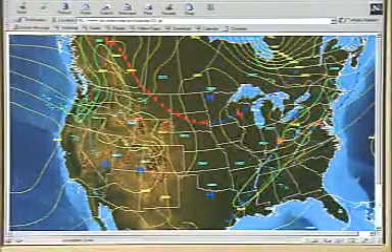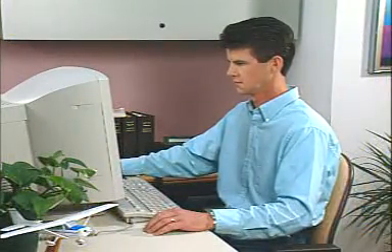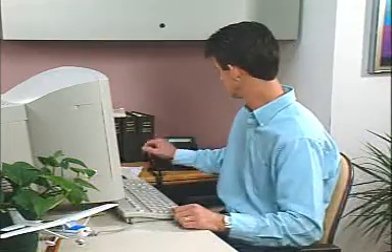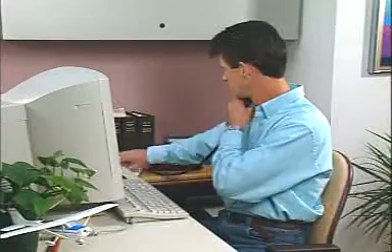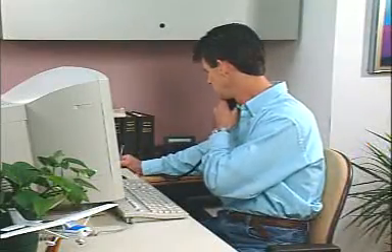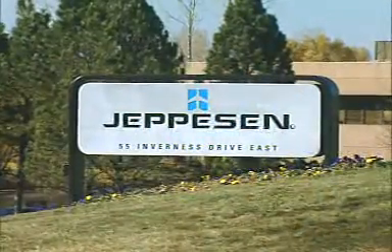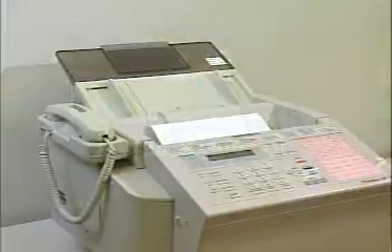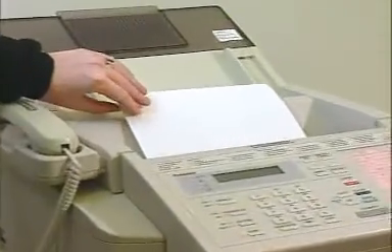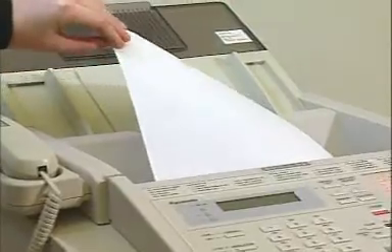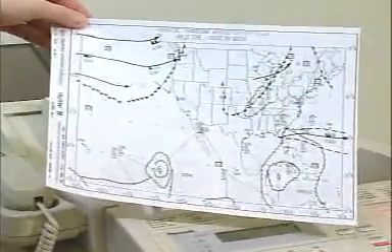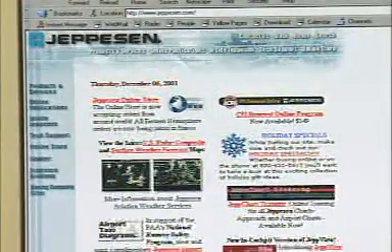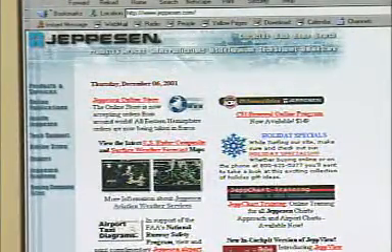government. While websites are excellent sources of pre-flight weather data, the information presented may not be the most up-to-date and should not be used in place of a complete weather briefing from an FSS or the DUATS system. Jeppesen also provides several weather resources for pilots, such as JEPFAX, a worldwide weather fax service available for a small user fee. A complete listing of Jeppesen weather products, including JEPFAX, can be found at jeppesen.com or at flightneeds.com.